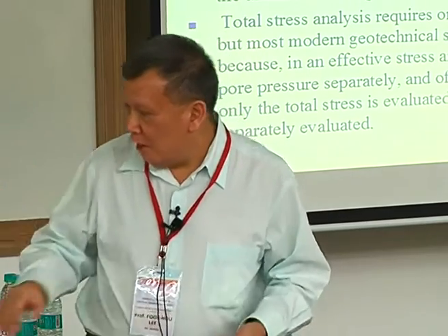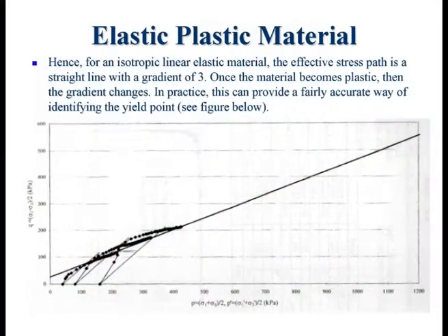Like just now I showed you that stress path. This is not something that's done for research. This was in a report dating back to 2004. I saw it for the Fort Canning Tunnel. It's a 16-meter diameter tunnel done using the New Austrian Tunnelling Method. We did the analysis for it. It was a 3-dimensional FEM and very sophisticated. We actually put in the forepoling, simulated the forepoling, simulated even the hardening of the shotcrete. It was done on Abaqus, okay? Because only Abaqus has the flexibility for it.